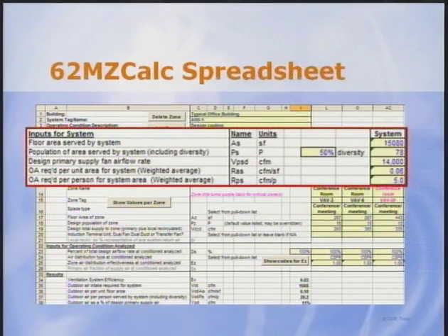All of these cells are populated automatically by the spreadsheet from the zone information listed below, but you can overwrite any of the cells if need be. All of the cells must be overwritten if you choose not to enter all of the zone data below, but more on that in a minute. If all zones are entered in the spreadsheet, you still will likely overwrite cell I9 for VAV systems, since the sum of zone airflow rates generally exceeds the design fan airflow rate due to diversity.